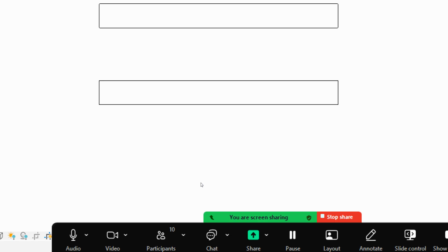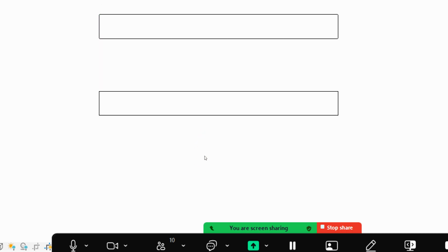So that one I can't say, because on the drawing maybe it says 12.5 millimeters, but on site the people who are laying the blocks may not be a little bit straight. So you must make it straight. Some places can be 12.5, can be 25 millimeters. That one there, it depends.